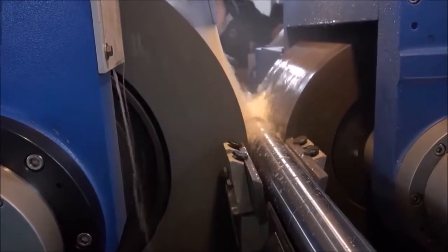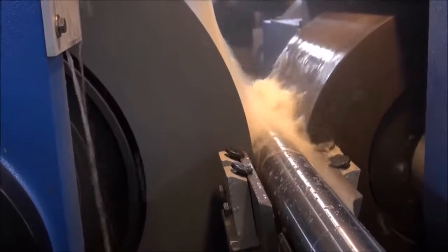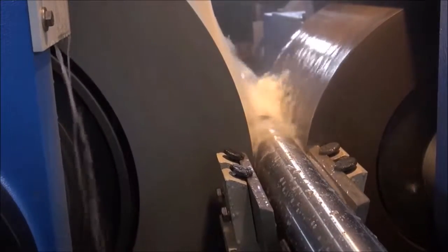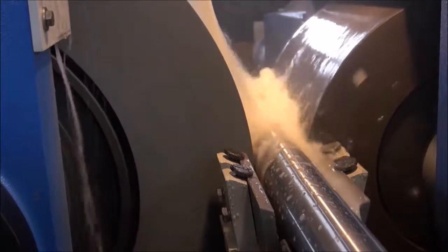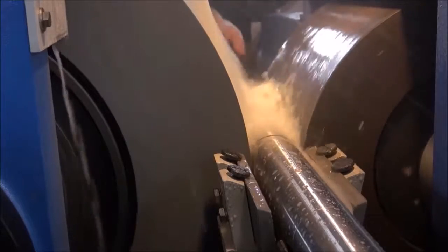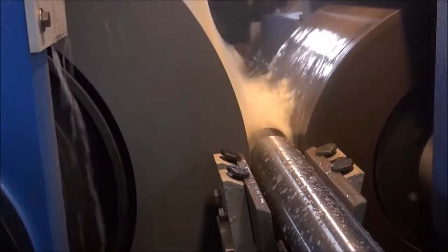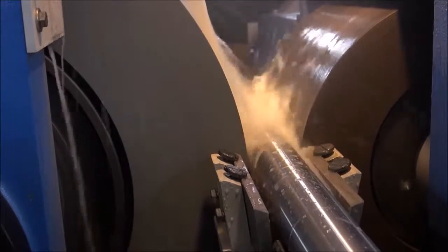In centerless grinding, the workpiece is not mechanically constrained. Instead, it is held in place on top of an angled work blade and in between a high-speed grinding wheel and slower rotating regulating wheel. The combination of these three key parts allows for any irregularities on the cylindrical workpiece to be evened out. When set up correctly, this process can rapidly create large amounts of incredibly precise, round surfaces.